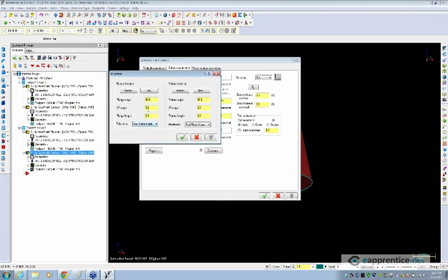So tool plane x-axis, we're going to do plunge angle 0, retract angle 0. We're going to do xy 0 and 0. Plunge length on the top we'll do 0.5, and retract length on the bottom we'll do 1.0.